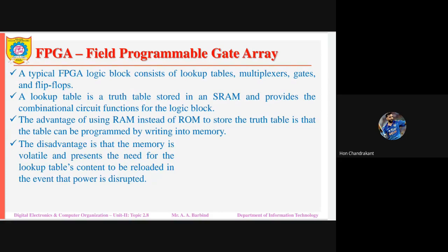It can be reloaded from the lookup table, or in other words, you can change the functionality of the FPGA again and again. Just by loading different data inside the RAM of the FPGA, you can change its functionality. So that is the difference between FPGA and PLDs.